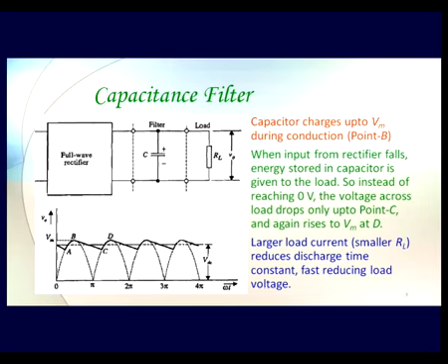because if you remember, the charging and discharging of capacitor is happening in exponential relationship, and that is dependent on the RC value of the circuit components. So that RC is called the time constant of the resistance capacitor circuit, and that RC time constant is the main determining factor in optimum design of our rectifier.